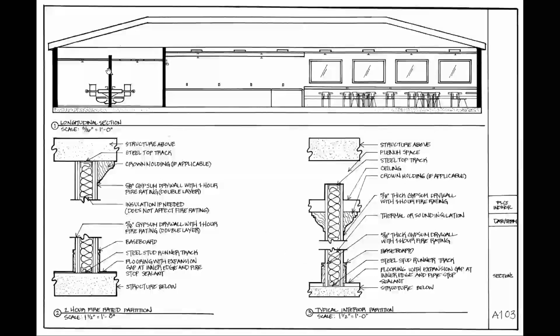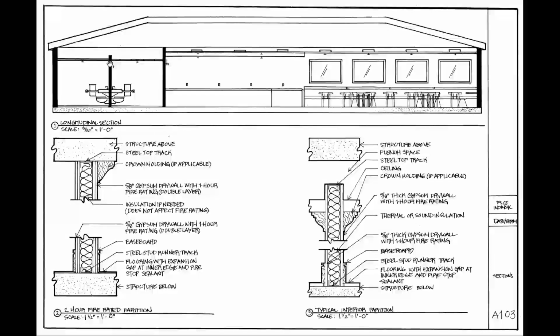It goes up to this ceiling, which is a drop ceiling. Okay, so it's an 8-foot ceiling. And then it goes up just a little bit above that, just to make sure that there's a clean break and some room for other stuff as needed, so you've got a little bit of extra space. And then the structural ceiling is above. Okay, and why do we build it like this? Because it's cheaper, it's easier, it's cheaper.